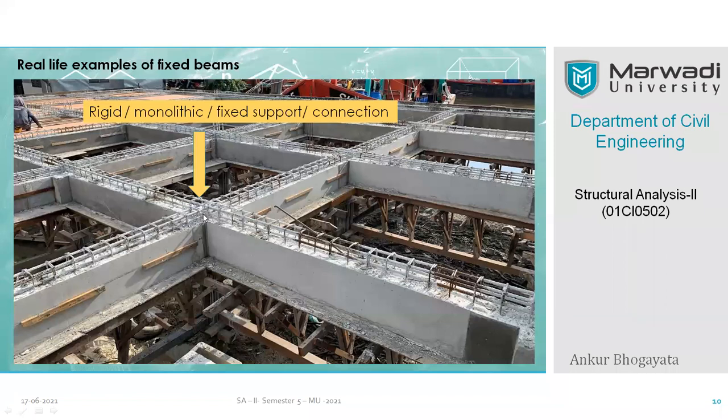When I cast my slab, everything goes inside, so everything is at the same level when I introduce my slab over this entire opening. Otherwise, if it is a semi-open area, you are going to cast this top portion together, and when you cast it together, you can develop a tremendous fixed joint.